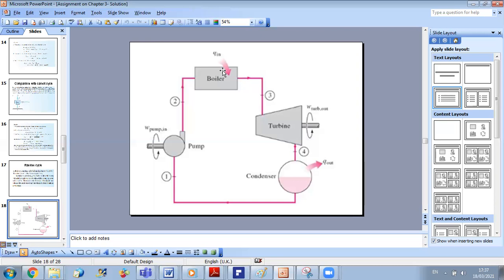In the previous session, we have seen together refrigeration systems. In refrigeration systems, it's totally the opposite. Here we are providing heat to produce work. In a refrigeration system, we are delivering electrical work to heat or cool. So when we calculate the efficiency, the output will be the cooling or heating, while the input is the electrical power provided. And in the case of a refrigeration system, we talk about coefficient of performance instead of efficiency.